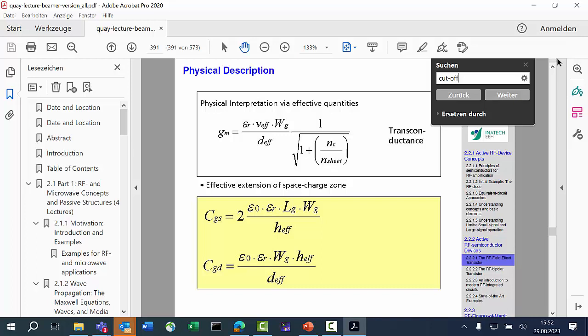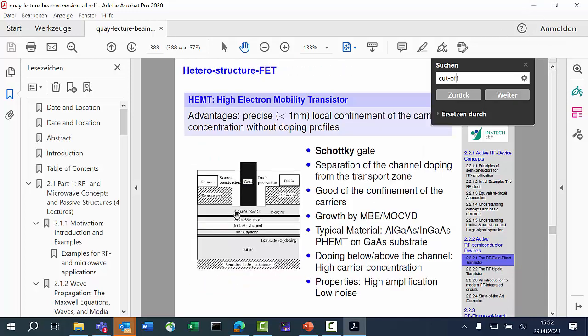The only way how you can make a transistor faster is to reduce its gate length, which is Lg, the length of the gate contact. This is why small transistors, especially in the gate length, matter. The gate length is this length here, from here to here, or in a CMOS, the same. So there's a contact, and you make the gate contact small. And that's why we need this lithography, which we talked about. That's the only way for any FET how you can make the device really faster.